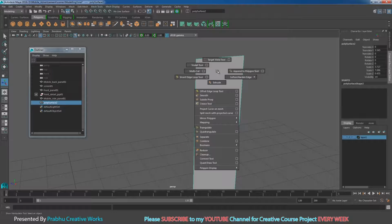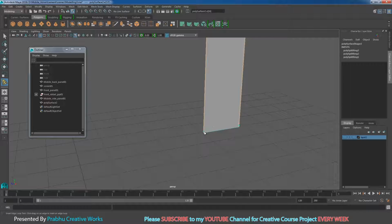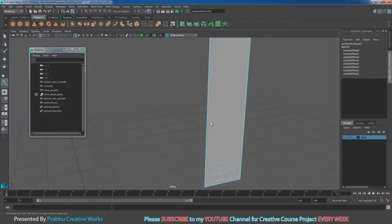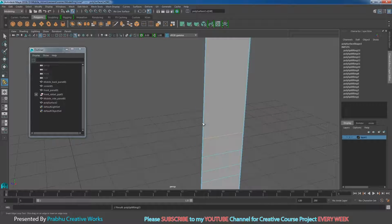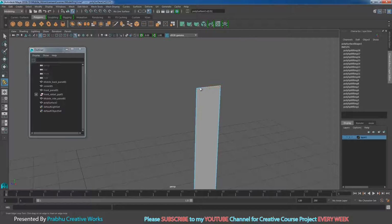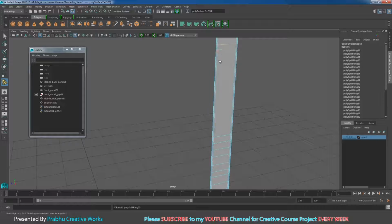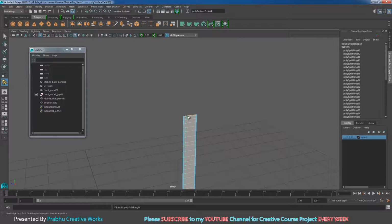Now we want to add insert edge loop very closely, as we did in the front panel. Like this, you want to add very close to here. You need to add a lot of divisions because we want to convert this object to a subdivision. When you convert any polygon object to NURBS, you want to add multiple edge loops, otherwise your object will be smooth in these corners. I want to maintain sharpness over here, so I will add multiple edge loops over here, and also here.